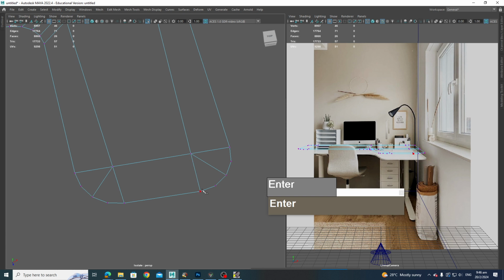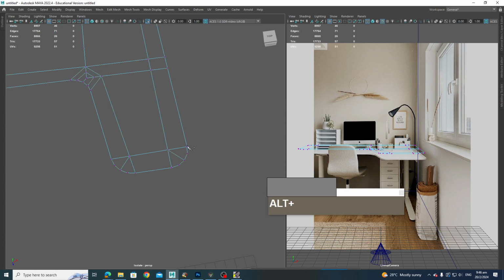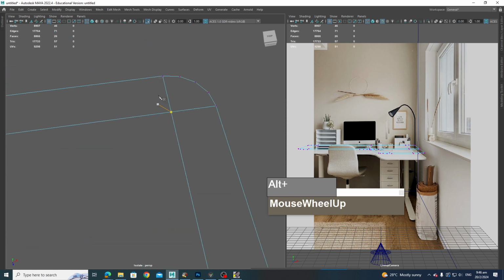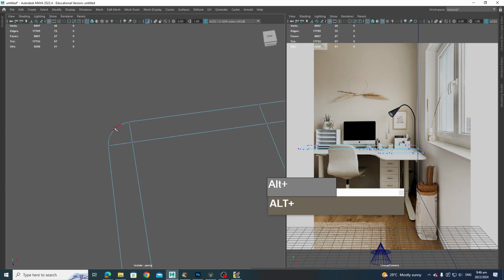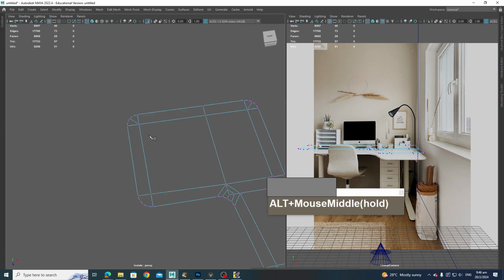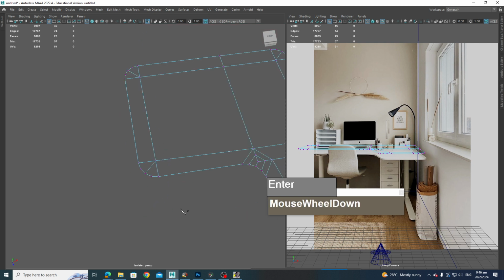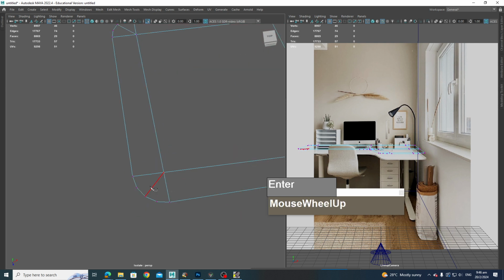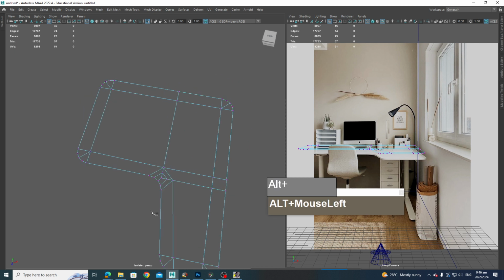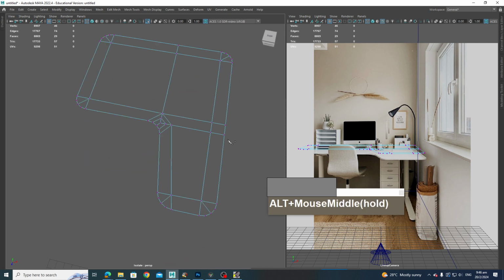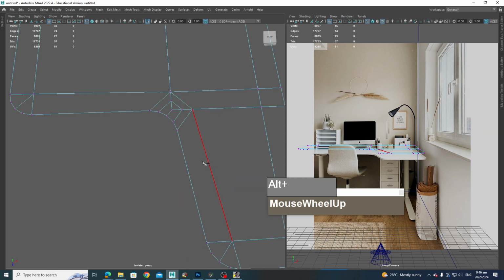By doing this, I've created these as 4-sided faces. You want to make sure that when you cut, you are splitting them and making them into 4-sided faces. So you have to do this for all the points like that. When you are beveling, make sure you bevel with an even number so that we can do this kind of triangular fence. It looks like triangles, but actually these are 4-sided faces as well. Alright, so we fix these 4-sided areas so they'll subdivide well.